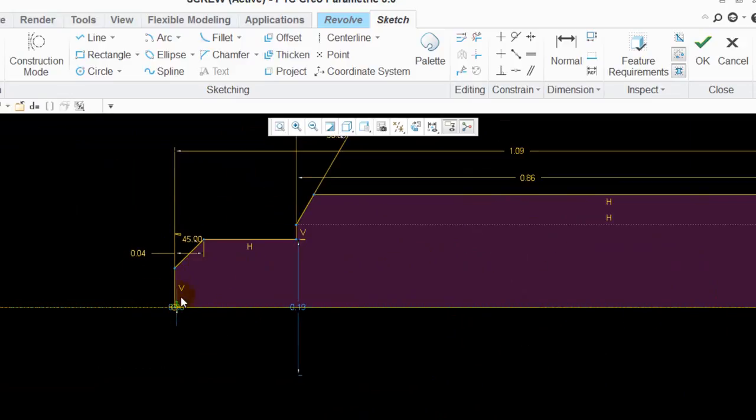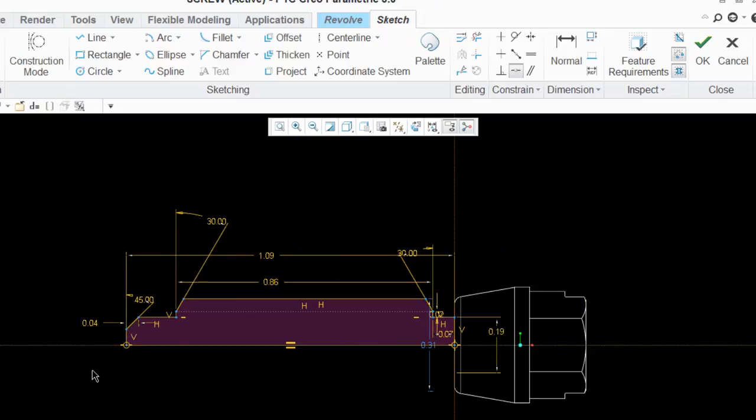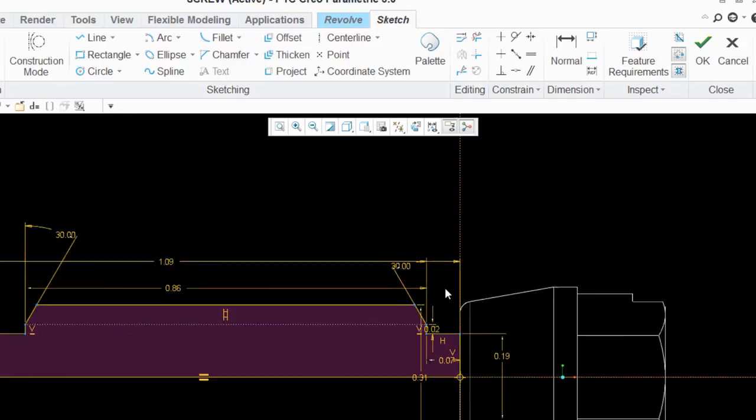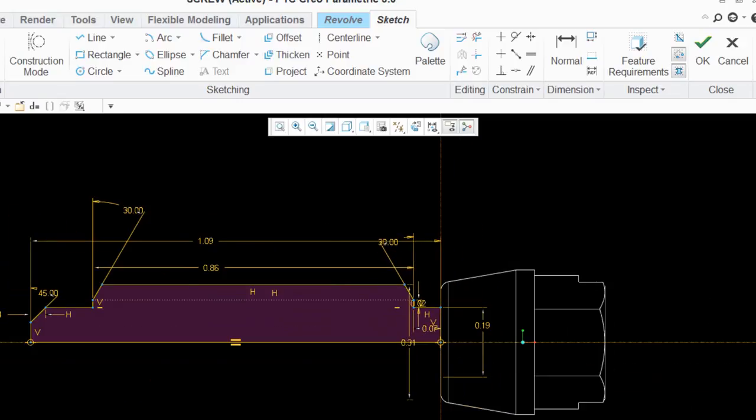Except for now, this is where we were before I found out. I just dragged it and I undid. Now I know what's wrong with it. I could just go ahead and line it up. So I'll pick the center line, and then I'll go here and then right click, and that's the reference. So now they're aligned, my 0 went away, and I'm only left with this weak 31. Let's make it a strong 31. Oh, 0.3125, that's what it's supposed to be. And that's all we need there.